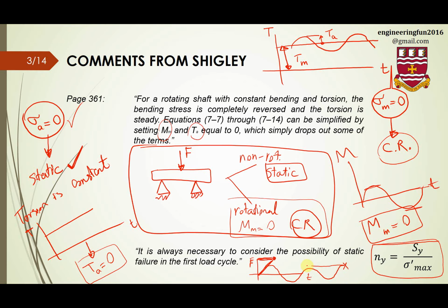So if I compare this amount, I'll see that this is less than my initial force that I needed. So the required force in the second scenario is less than the first one. It means that I could go to failure with less force acting on the material, and this is because I had a cyclic load on the material.